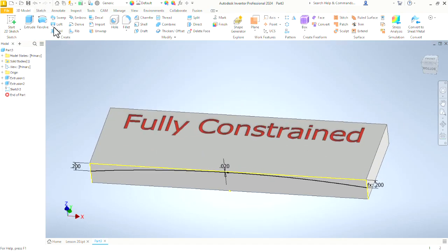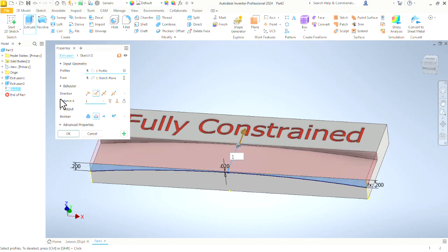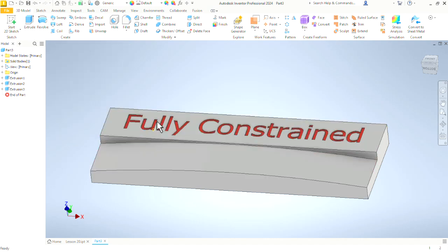Finish that sketch. And as we went along, it created these lines around the outside. So when we start an extrude, that will automatically select that profile. We want to start cutting into the part. It is set for cut. We made the part 2 inches wide, so let's cut halfway through with a 1 inch dimension.